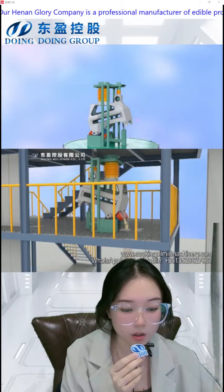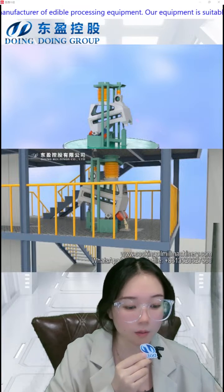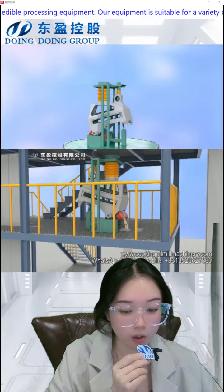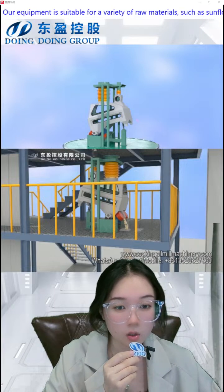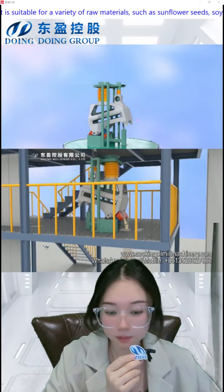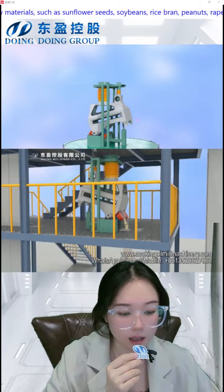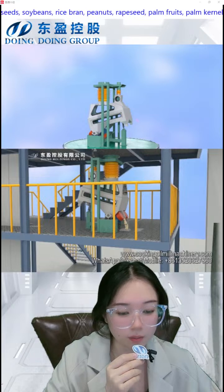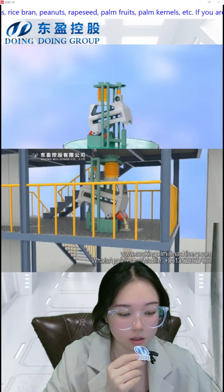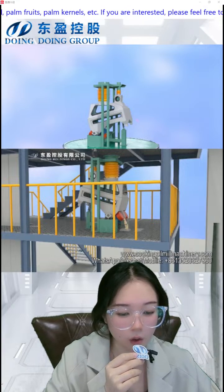Generally, customers have requirements for the impurity content of raw materials when processing them. For oil processing, we usually require the cotton seeds to have an impurity content of less than 3%. For shelled oilseeds such as cottonseed and sunflower seeds, it is necessary to use a huller to remove the outer shell. The presence of the outer shell can also absorb the oil, affecting the oil yield.